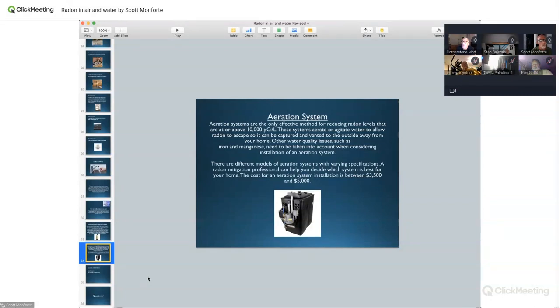And again, you should always recommend having a certified person come out and service the unit. The aeration system should be cleaned once a year. Bacteria, they have solenoid valves. The filters can be cleaned or changed. There's a filter on this one. There's a filter on this aerator.